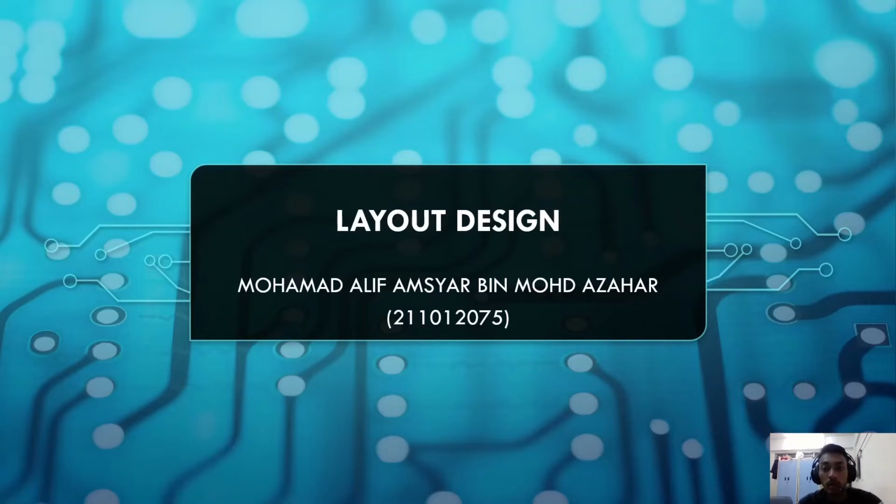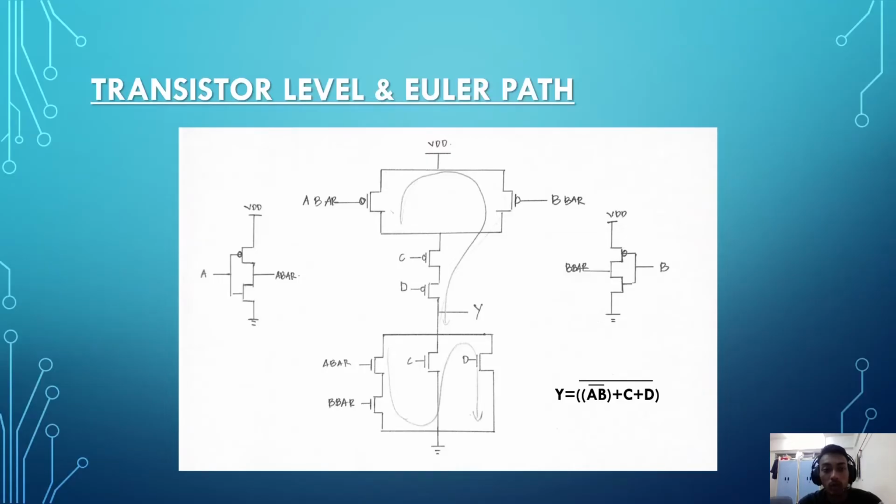So for my part, I will present the layout design. First, the transistor level and the Euler path. From the equation, the A and B inputs have bars. So for these inputs, we need inverters to convert A to A bar, B to B bar. As you can see in the diagram, we use about 12 transistors here.